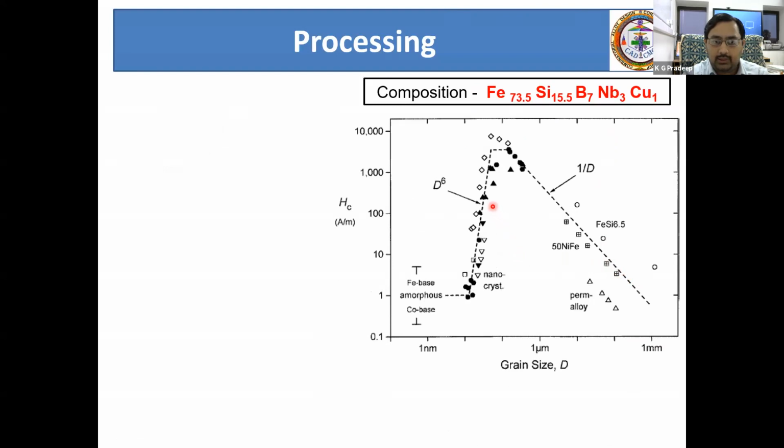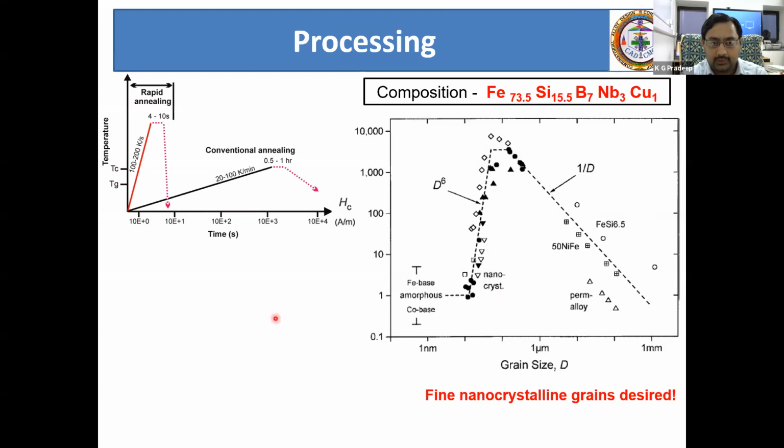If the coercivity needs to be low, then the material has to be almost in a nanocrystalline state or in a millimeter grain size. So the moment we go into nanocrystalline states, it cannot be produced in a bulk form in a nanocrystalline state. It has to be produced by special methods. So one such method is that this combination of metals can be melted, and this can be made in the form of a thin film.